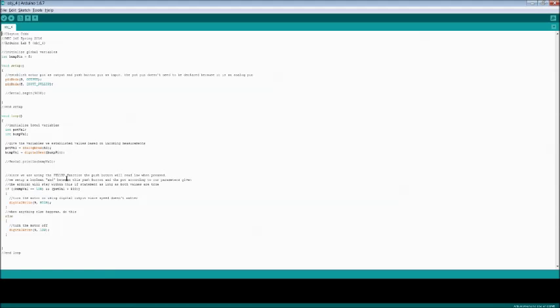As I stated here, since we are using the pull-up, the bumper switch value, in order to say something is true when it is pressed, needs to be equal to low or 0, because the pull-up is always keeping it at high when the circuit is open. This is in an if statement, Boolean ANDed with a potentiometer value greater than 500.